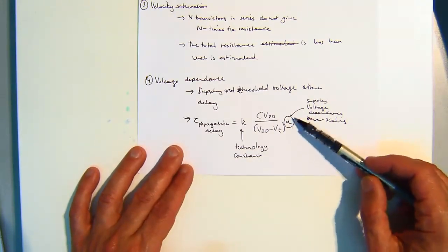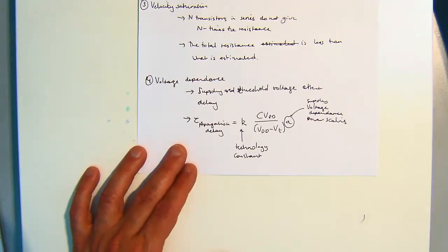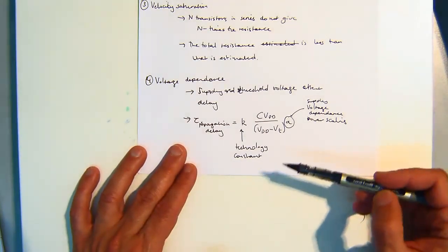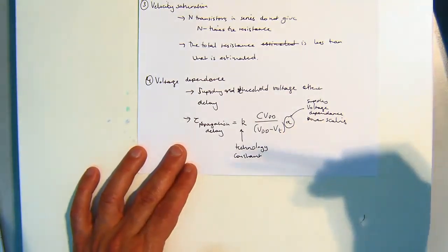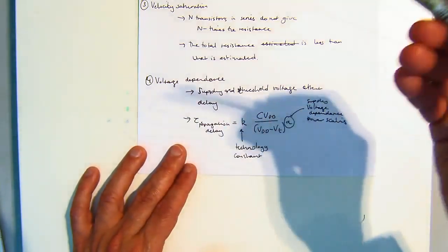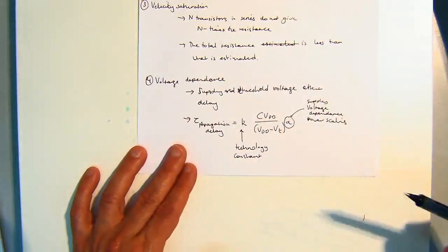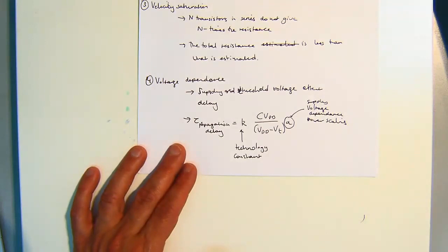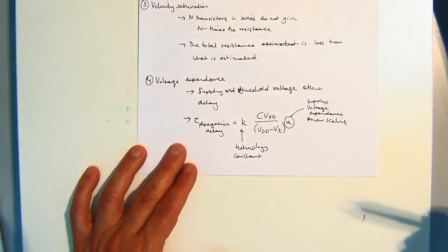So what you would normally do, in your standard cell library, or if you were doing a layout and a parasitic extraction as part of your design, is choose a supply voltage and then work out what you would expect the propagation delay for an inverter with that supply voltage to be. Because you can't just say, I'm at 3/4 of a volt, so therefore my propagation delay is going to be 3/4 or something. It's got a non-linear relationship.